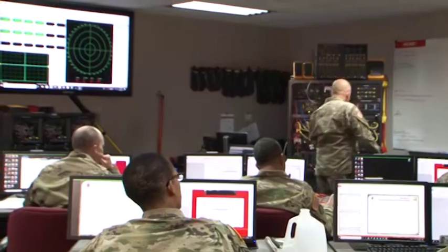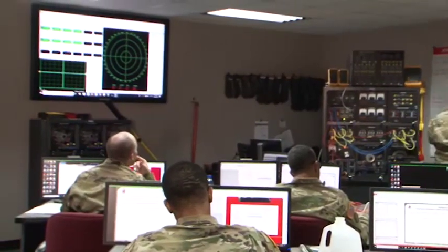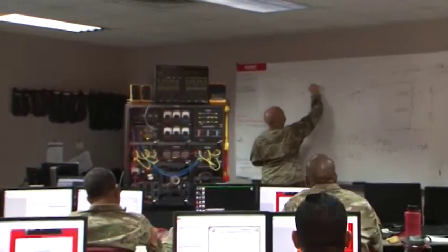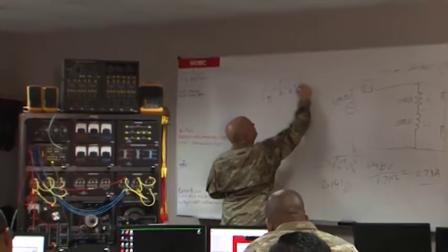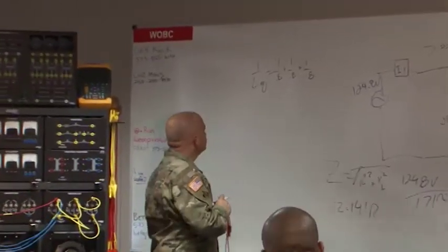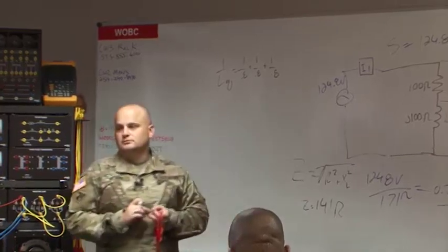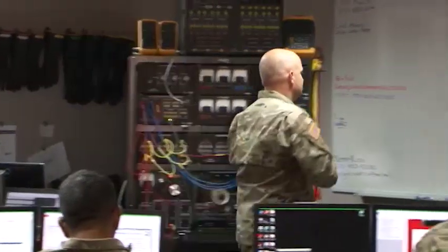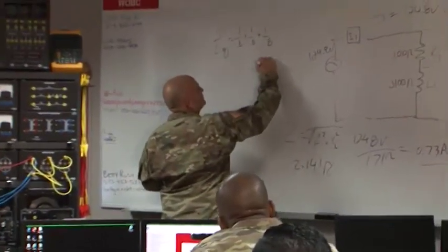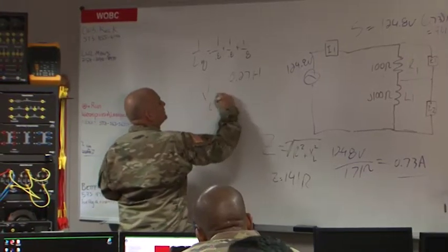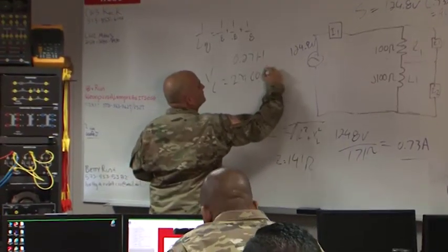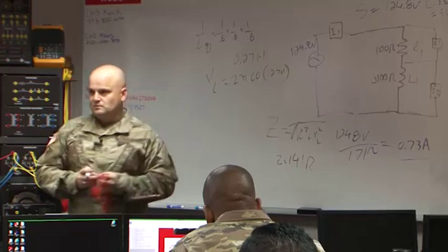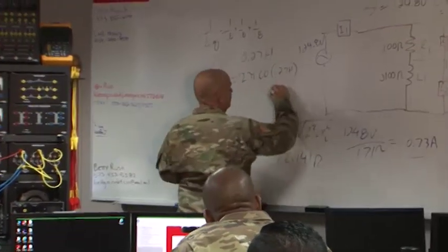See that? So I got 0.8 henrys, 3 of them in parallel. Let's confirm our numbers. 1 over L_eq equals 1 over 0.8 plus 1 over 0.8 plus 1 over 0.8. What does that equal? 0.27 henrys. So now if I want to know X_L, it equals 2 pi times 60 times 0.27 henrys. What's that? 100.5. Okay, so we're at that 100 level.